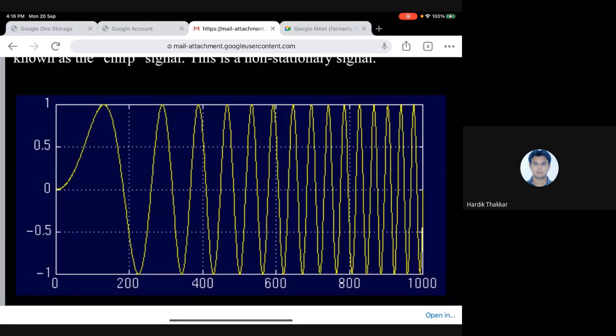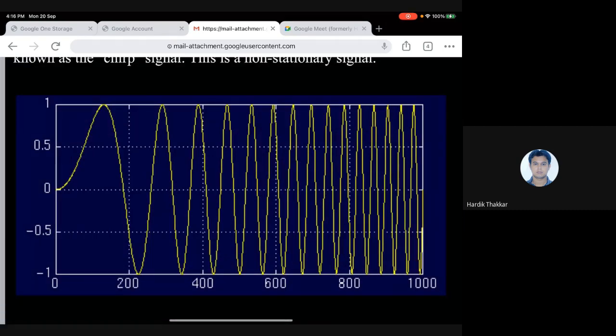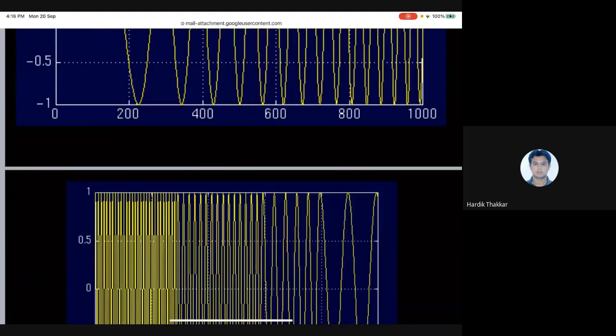Simply, as I described the one above, if you look at this signal, you would say it looks like a chirp signal. Its frequency is slowly increasing, it ranges from 0 to 1000 milliseconds, and its amplitude is +2 to -1. That is all you can tell. But you cannot tell what frequency components are present, right? Then what will I do? I'll apply the FFT again.